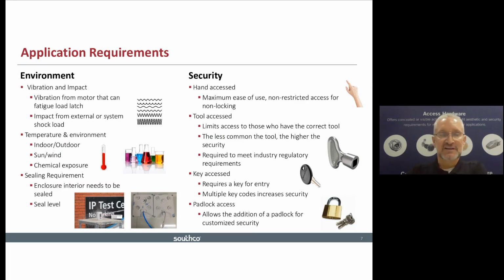So first of all, some of the questions you might ask your customers when trying to figure out what compression latch they should use are some of these here. So what environment will your latch or application see? Will it be under a constant vibration from a motor load, or maybe a sudden or distinct impact for shock load? The former can speak to how well your application or latch can hold up over time, and the latter can speak to how strong that latch is to withstand certain and sudden impacts.